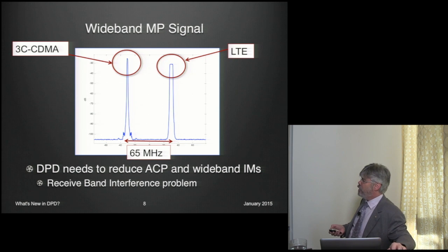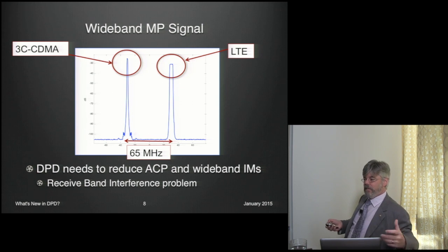What do I mean by wideband multi-protocol signals? When I started as DML about 3 years ago, this was the challenging signal. This is the Sprint signal. Sprint, through no fault of their own really, ended up owning bits of spectrum at each end of band 2. This is 1900 megahertz. So they owned a bit down here at 1930 and another bit up here at 1990.